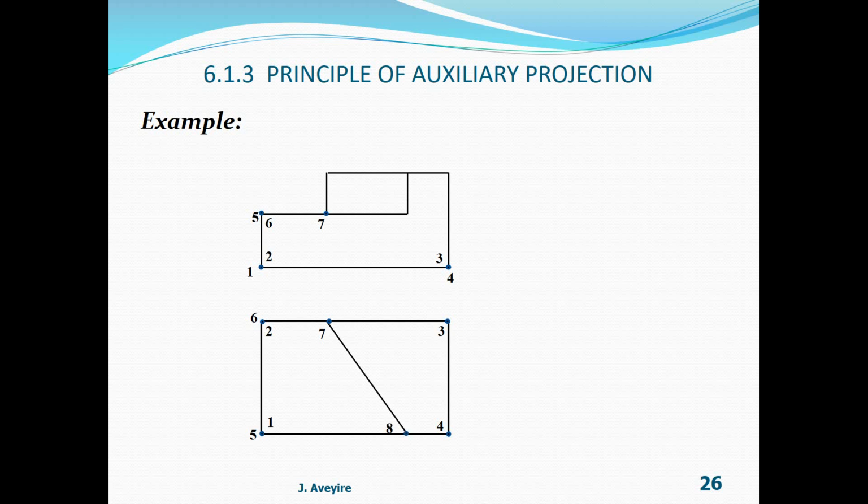8 is here. From this, we know 8 is not visible on the top view because we know there is an edge directly above 8. Therefore, it's not. But in the front view, it will be visible. 9. 9 is directly above 8. So that's the top surface of the top view, and therefore going to be visible on the top view, and in the front, because 9 is in front, is going to be visible.